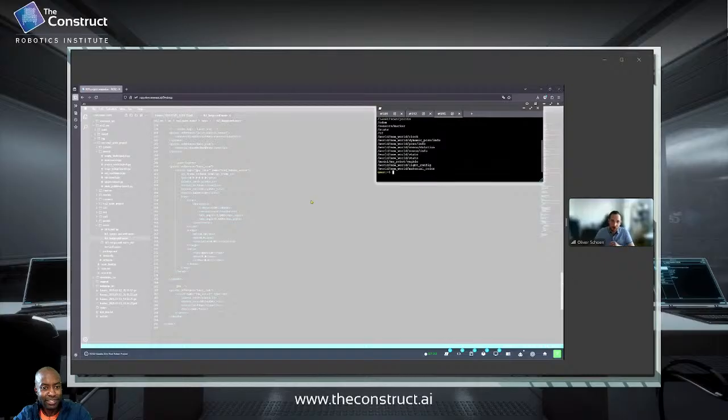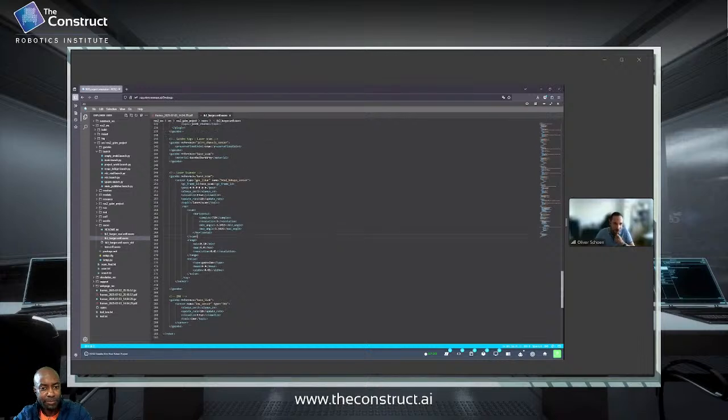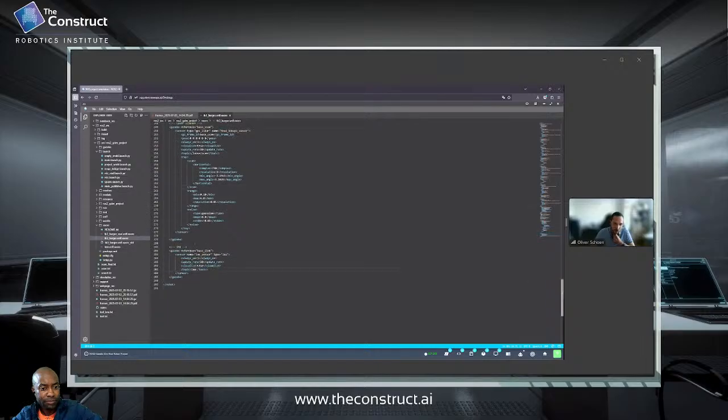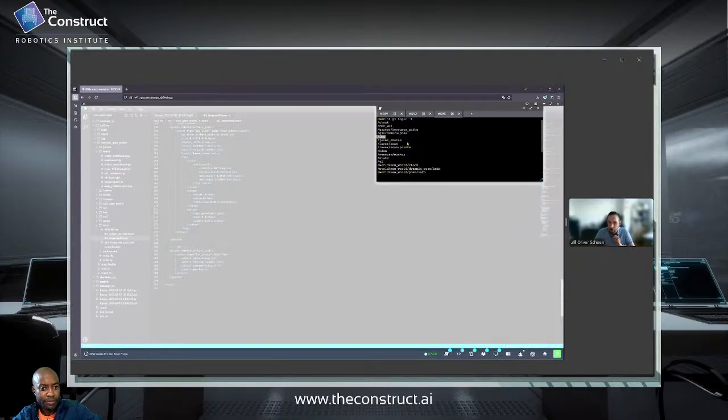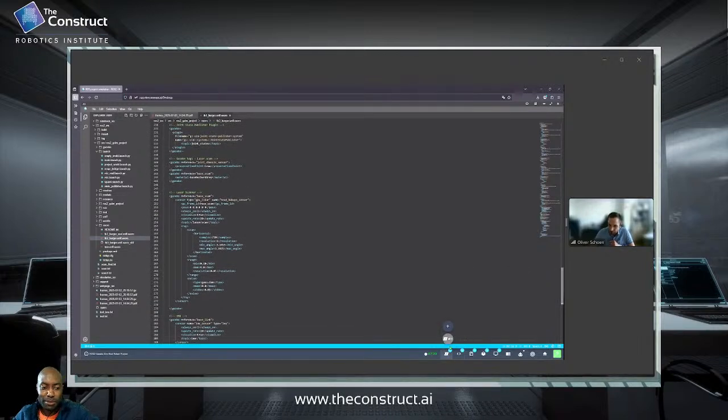But I had difficulties with the frame, and this was giving me a lot of errors in RViz later, even though the information was received on the ROS2 side. Then I found that I had to define this Gazebo frame ID so that it does not take the base scan and the head Hokuyo sensor as a concatenated thing, but just takes the base scan as a frame. And then it was working fine. So this was more about the frame part. It was not about the topics specifically, but of course frames. In these plugins you decide which topics are published. For example, in the IMU it says you use the topic imu, and as you can see, we also have the IMU topic in Gazebo. I don't know if this answered your question. It was a bit more about the frames. There might be differences between the robot and the way the frames are mapped to Gazebo. Yes, I understand. All right.